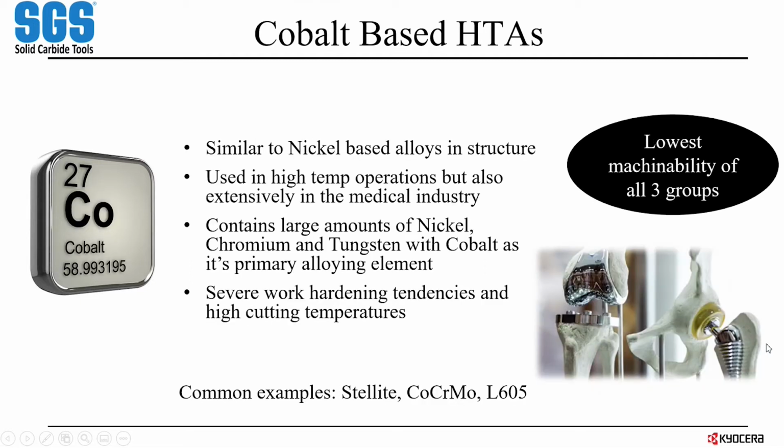Next up is the cobalt based. So this is, I won't say obscure, but you just don't see cobalt alloys quite as much. And that's a lot to do with the fact that they have a very low machinability, even compared to the nickel based stuff. There's also more expense involved typically, but they do hold up very, very well under high temp operations. But you'll also see it a lot in medical. Cobalt chrome alloys are very, very heavily used in the medical industry.